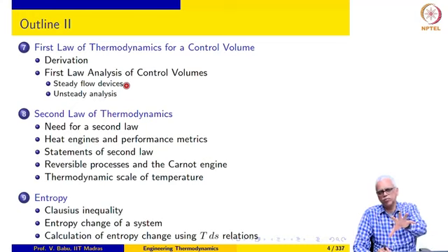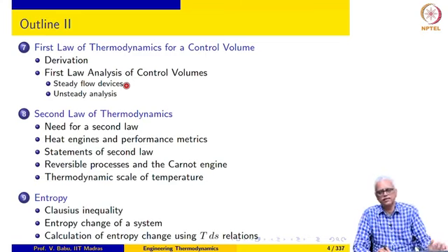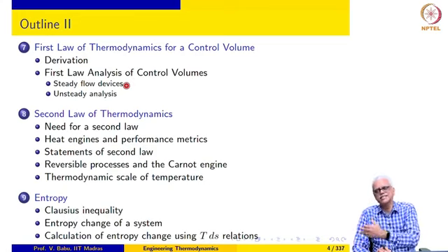For instance, in this example, we said that the compressor compresses the air and then sends it to a reservoir. So, if I want to carry out a thermodynamic analysis of the reservoir, note that the reservoir continuously receives air, but nothing leaves. So, it is operating in an unsteady state. So, we may want to know what the final pressure of the air will be after some time in the reservoir. This means that the pressure of the air in the reservoir keeps changing with time, and we want to determine what this pressure is. So, that calls for an unsteady analysis.